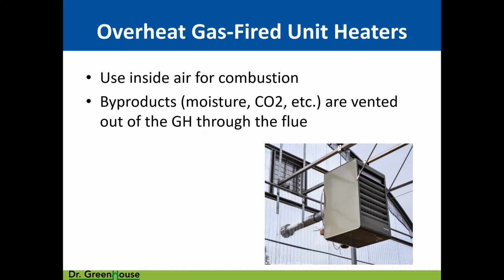I mentioned already we can use overhead gas-fired unit heaters and use that inside air for combustion, as opposed to bringing in outside air for combustion, and then relieving that water vapor and the other byproducts to the outside through a flue. We would then infiltrate, and what would happen is that air that was used for combustion would then suck some air also from the outside through infiltration, which we would hope would be drier than what's inside. And that's partly why we would need the heating, especially if it was 20 degrees outside.